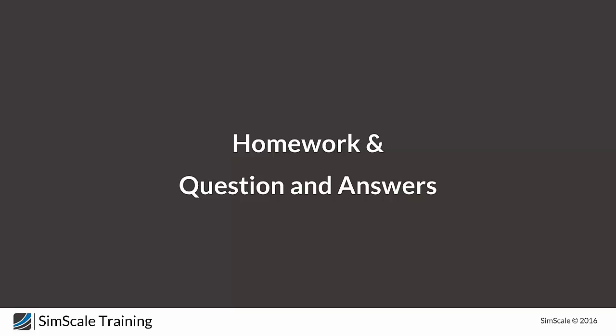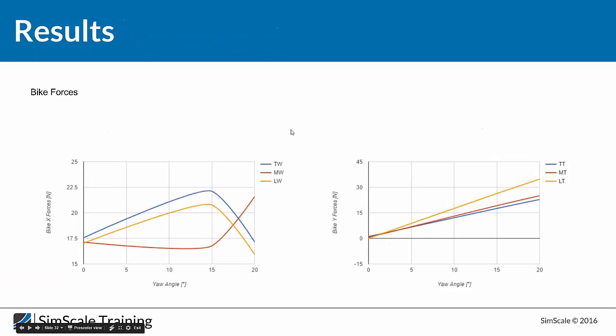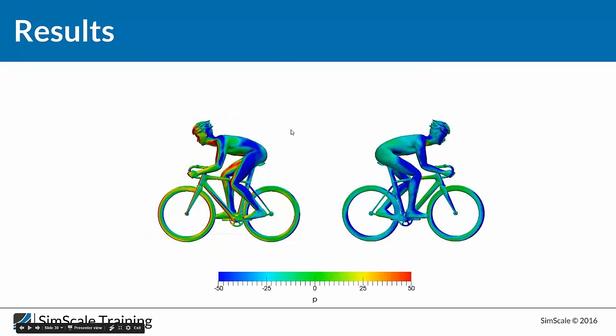Okay, guys, there is really the final question by Fabio. He wants to know, the medium-sized wheel in one graph showed completely opposite behavior than the thin and the large. Is there a reason? Yeah, that's right. I see. Actually, I've checked the results closely, and I've seen that there is a difference just here. If we look at the wheel and the tire, there is a small gap, and this gap really creates separation over there, and I guess this is the reason. Yeah, I think this is the reason why.